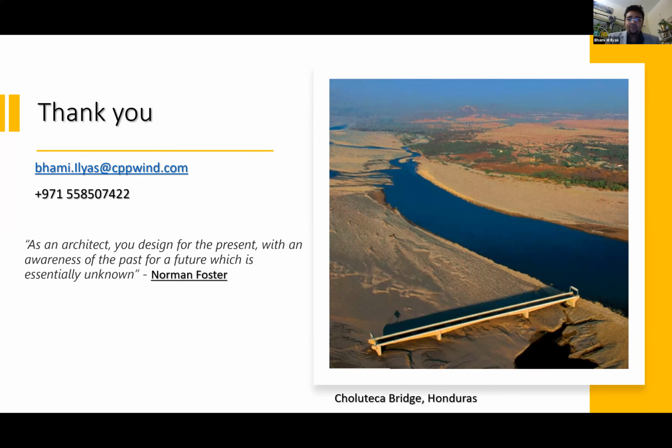Okay, another question from Abdullah. There are positive and negative wind pressures. Which one is usually bigger and why? Again, Abdullah, very nice question. Typically it's difficult to say any one is dominating, but negative pressures, the suction, we tend to find on a given facade or elevation of a project, maybe on the higher end. Nevertheless, we have also seen positive pressures going up really high. But in general, I have seen negative pressures, suctions, go really high.